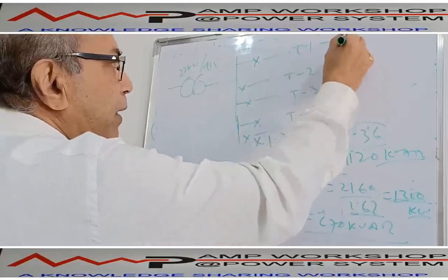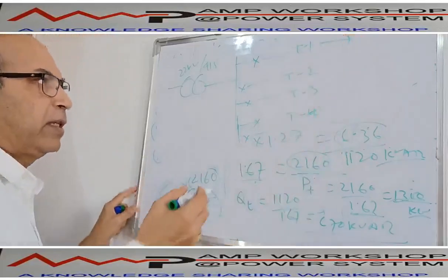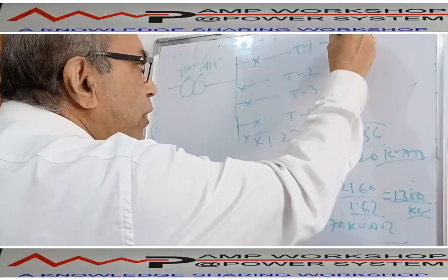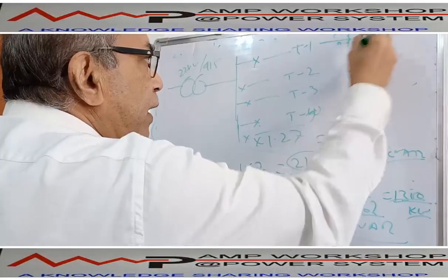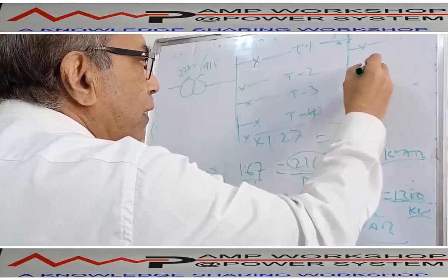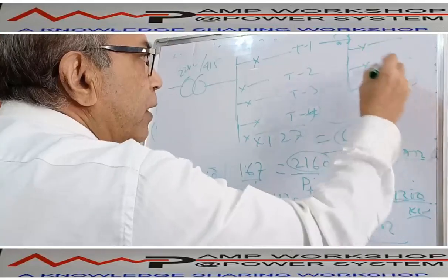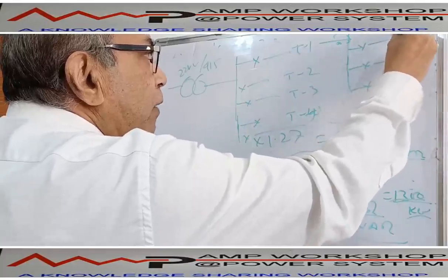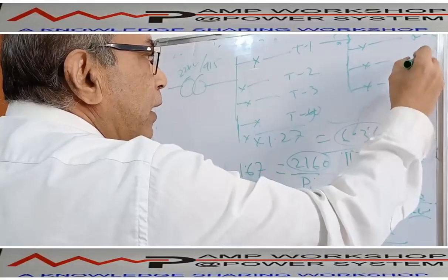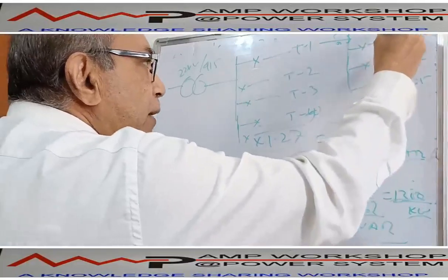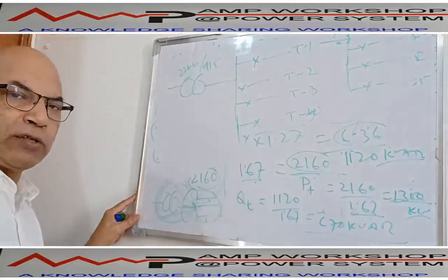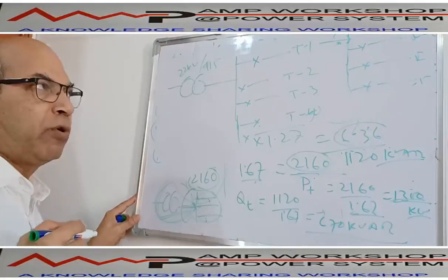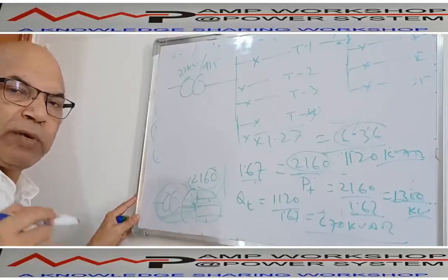Now from here, again, I will consider that part separately. From tower 1 it is going to another distribution board over here. From here maybe a different feeder goes for each floor. Each floor has one feeder. This one is going to floor 1, floor 2, floor 3, floor 4, like that. Floor 1 has how many apartments? We have considered a 20-story building with 5 apartments on each floor, so 5 apartments on each floor means 100 apartments.